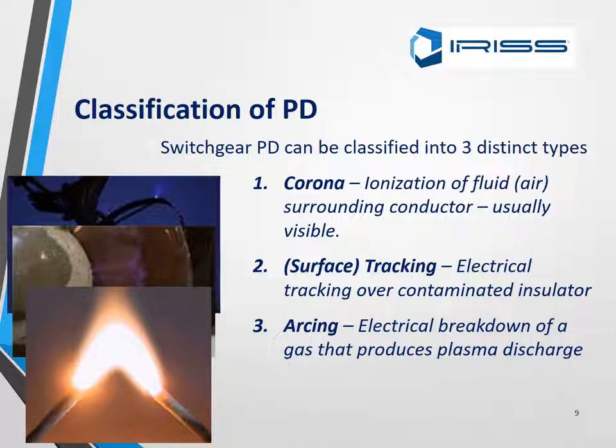Secondly, you can hear it through EPD, through ultrasound, and also you will be able to start picking up the small heats via IR. And thirdly, arcing. Arcing has a distinctive sound, but can be picked up via PD, definitely be picked up by ultrasound, and definitely can be picked up by infrared.